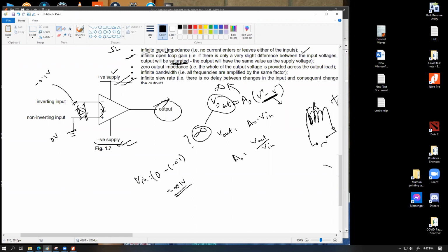Precisely. So if I connect the non-inverting input over here, and for this inverting input, other than connecting a fixed voltage, you provide an AC supply of, let's say, 0.1 volt at 50 hertz, in that case the output is going to give us the saturated voltage value with a 50 hertz output.